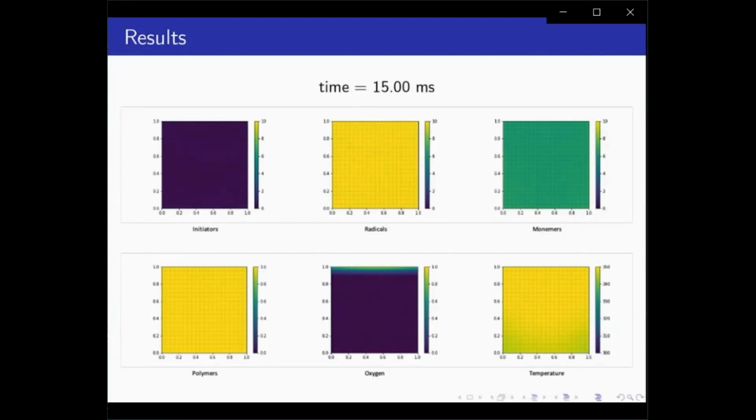The results are reasonable, and we can notice exothermic polymerization reaction in the temperature distribution figure for the sample. Something that we noticed for the actual values of reaction coefficients, you get a very fast reaction and a very slow diffusion. As a result of that, you have a very fast initial dynamics related to the reaction process, while getting a stationary state is only very slow.